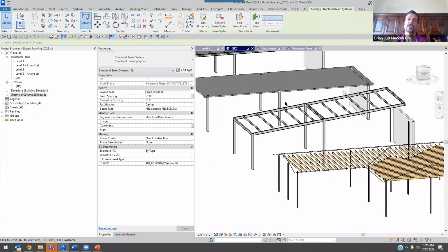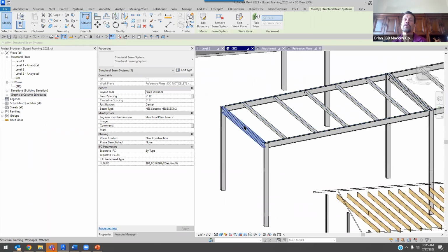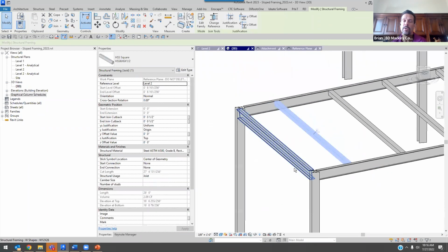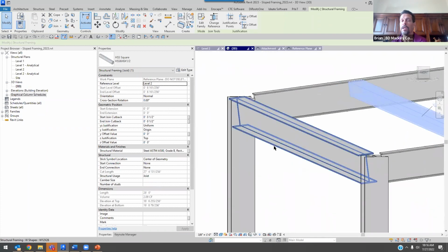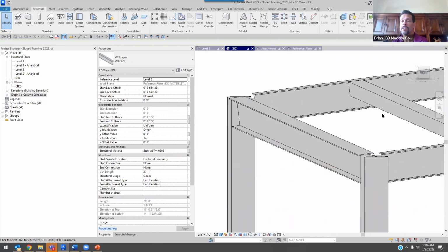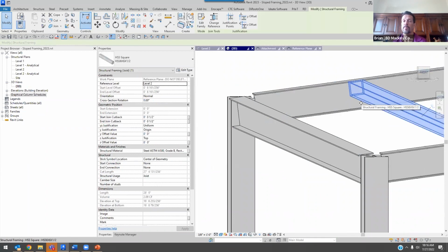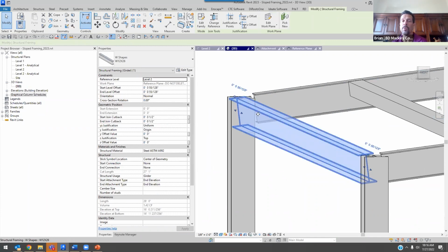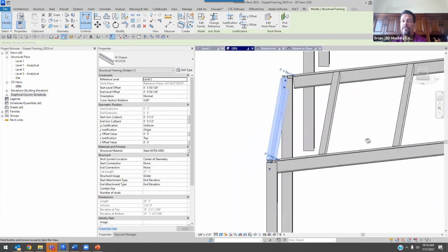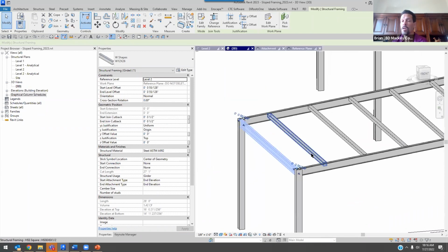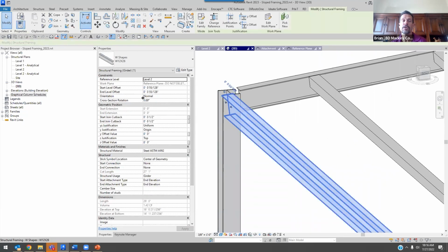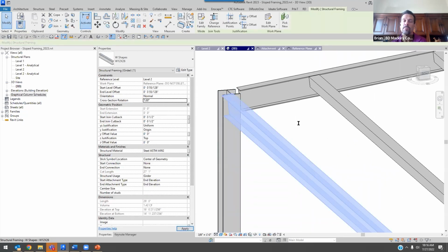Now, one advantage, or disadvantage, depending on what you're doing, if I start looking at this, you can see that when I use a sloping reference plane, all of these members become perpendicular to that reference plane. So it might make sense to have all these intermediate beams chosen to be perpendicular to that reference plane, but the problem is it's going to do all of them that way. So you'll notice that these ones are all going to be rotated at 5 or 7 degrees or whatever I have that slope in that beam. This might be exactly what you wanted, but if you needed one, like in this case, to be plumb, then you're going to have to start coming back and relying on that cross-section rotation. I think I was 7 degrees, -7 here.